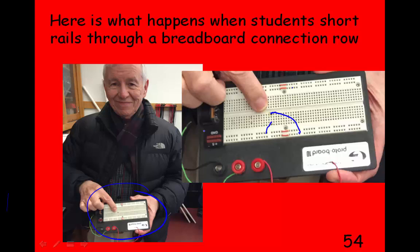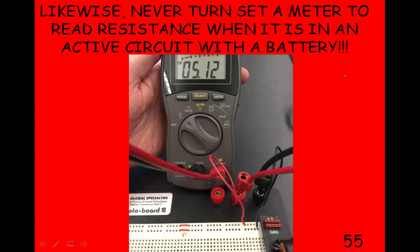So they just connected the positive 5 to ground and ran it through that little connection row. These breadboards are not designed to take large currents, and it actually burned the breadboard and ruined it. We couldn't use it again, and that cost our department $100. So that was another thing you should never do.